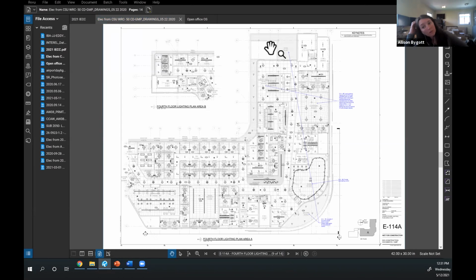And, you know, periodically you need to check that all this stuff is being maintained. You need to check that daylight sensors are still accurately reading and working. You know, if you have a system with batteries in the devices, if you have battery failure, you're periodically going to need to change batteries. A lot of manufacturers will say they last 10 years. We're finding it's more like 5. You know, what does failure look like in that situation? But it's the owner's system to maintain, and periodically it's helpful to have someone come back and just make sure things are working right.